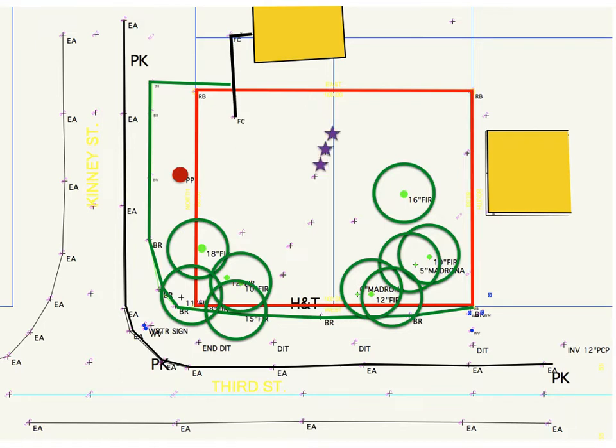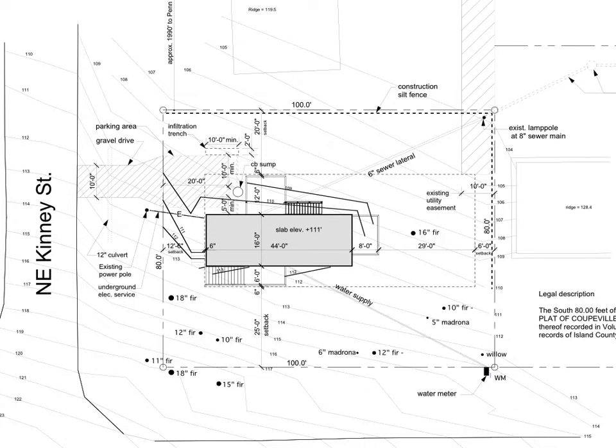And then finally, the topography. These are the spot grades. A surveyor does not go out there and try to draw contours while on site. Surveyors take what are called spot grades. They shoot the elevation at specific points, which they map carefully, and then they can later go back and construct the existing topographic lines and contour lines from that data. And we'll get back to that in a little while about how to do that.